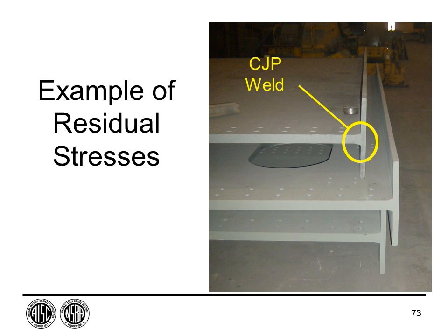Another really powerful way to see this is in the shop. This is a web of a girder with a small flange placed on it. This is probably some kind of diaphragm. And this is what's called a CJP, or complete joint penetration weld. So this is all weld metal in here to join these two plates together. Now, notice this is a nice straight flat plate, perfectly perpendicular to this. But there's a lot of residual stresses here.